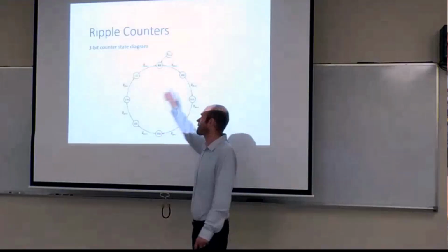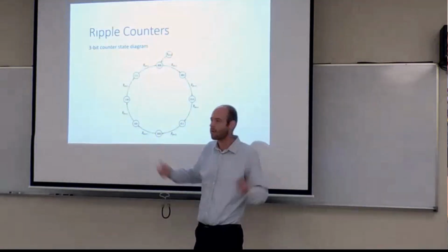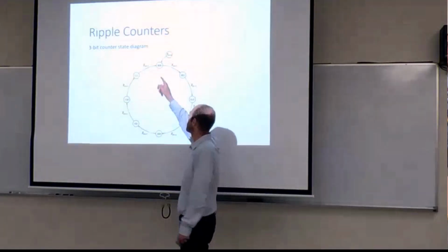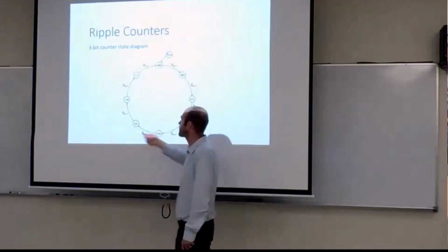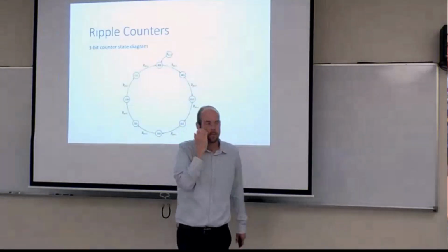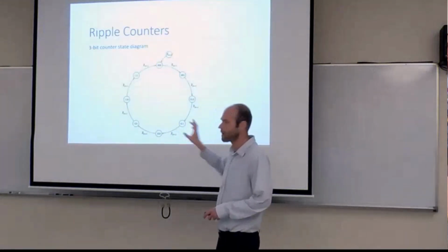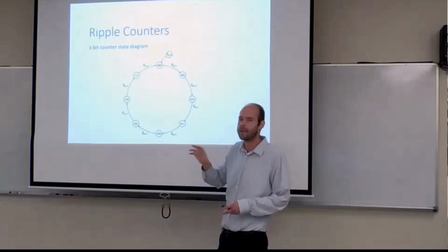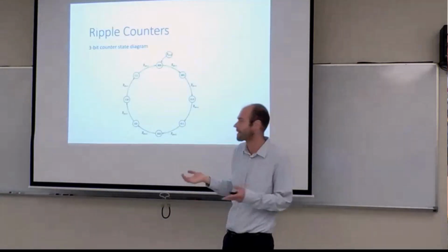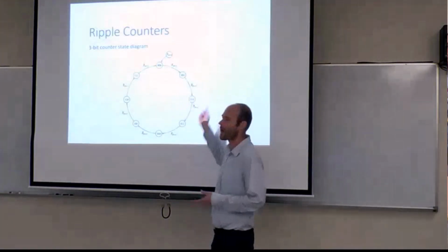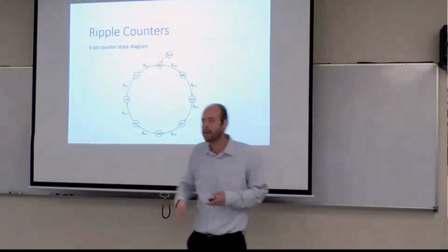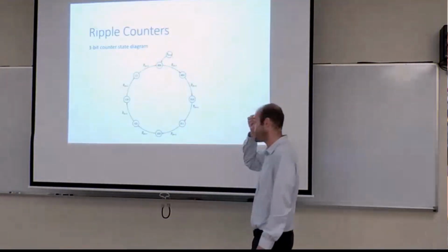You can visualize the counter as a whole in a state diagram style, which is just starting at 0, 0, 0 and moving through those states. We will use state diagrams a little more later when our state movement is more complex. Right now, there's only one path. It's directly around in a ring. So it's not mandatory that we view it in this way.